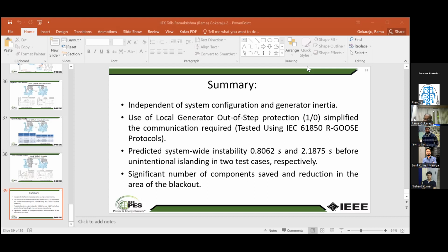If they don't become equal until 149 degrees, then because of measurement errors, we may predict it as unstable. That is all right. But if we predict it as stable, then it will be a problem. So we have to have an adequate margin to prevent this false prediction. Sunil, does it answer your question? Yes, sir. Thank you, sir.